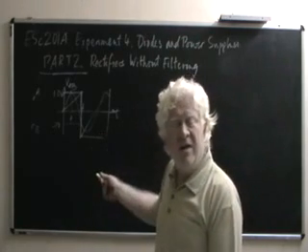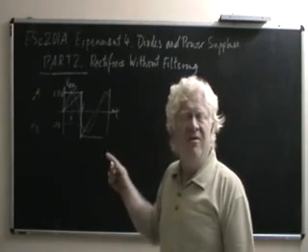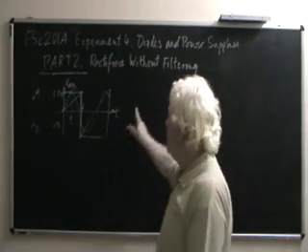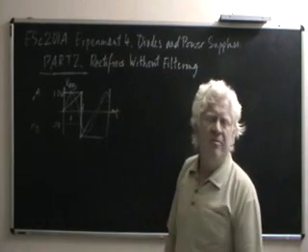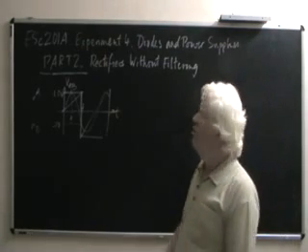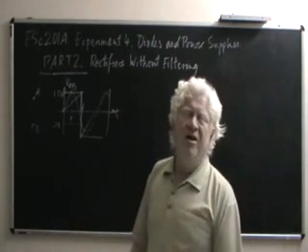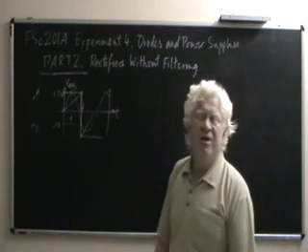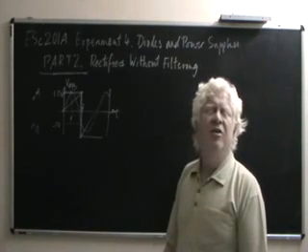The first step we take, that is just a rectifier without additional circuits, will convert a bidirectional or alternating signal into a unidirectional signal. The way we do it is using a diode. That was the reason why we studied diodes in the first part of this experiment, because a diode is inherently unidirectional.